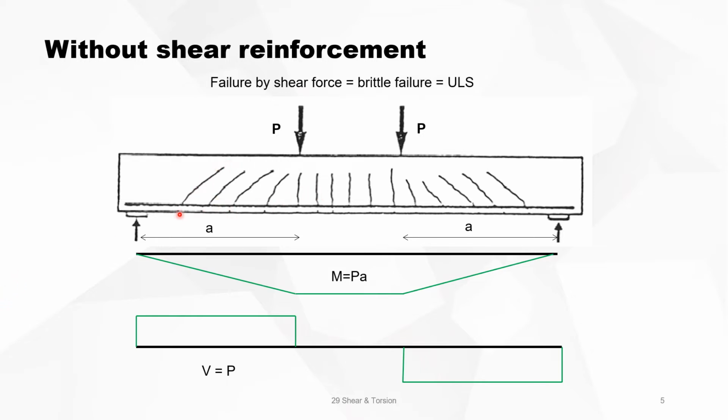Those cracks due to shear force appear suddenly, so there's no warning system. So a failure by shear force is really a brittle failure, so it is a ULS situation. You do not handle shear force in SLS.